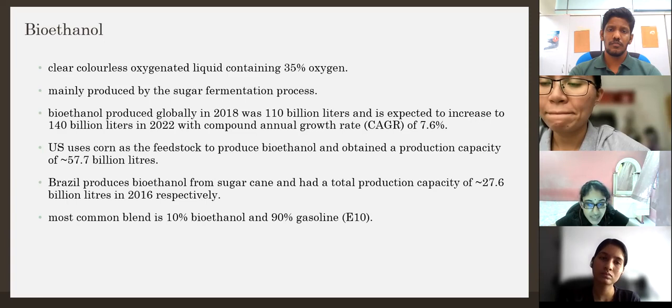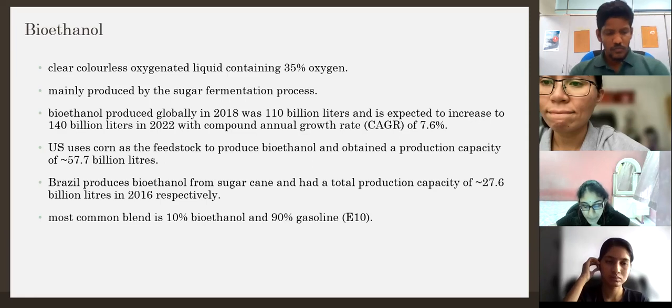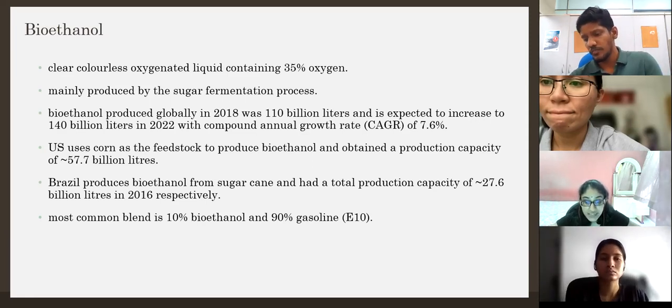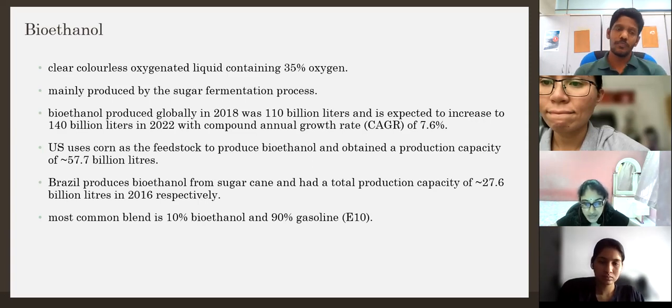So the disadvantages of bioethanol: it possesses low volumetric density, meaning that more volume of bioethanol per kilometer, up to 50% more, will be consumed compared to conventional gasoline. Besides that, the use of bioethanol in engines might also require frequent replacing of engine parts, as bioethanol has the capacity to degrade some elastomers and cause corrosion of metals.